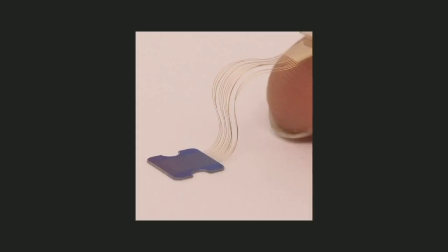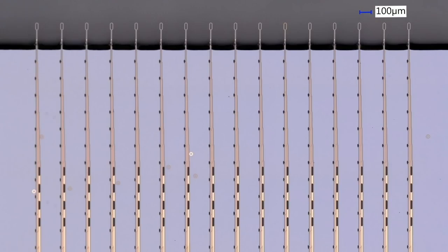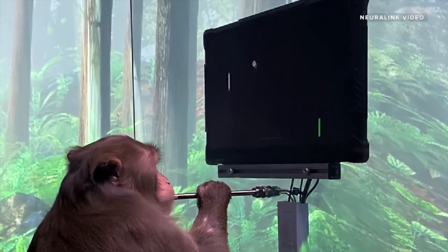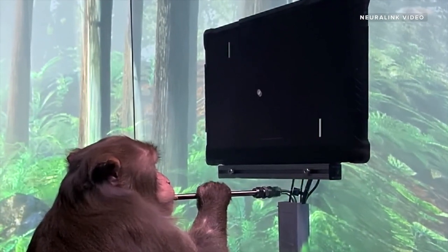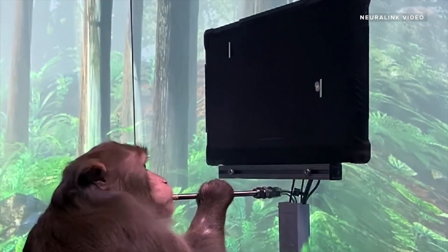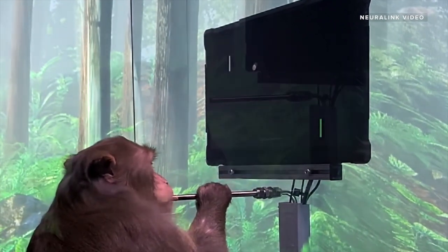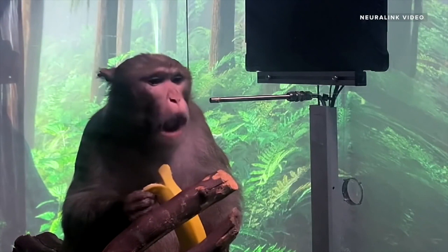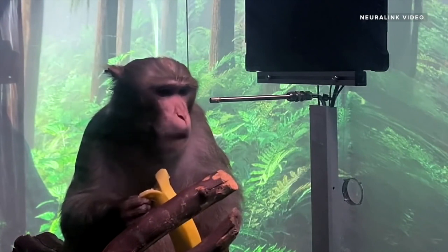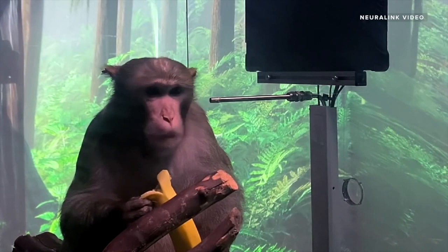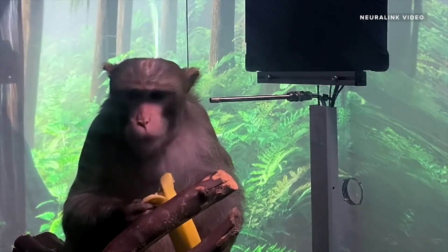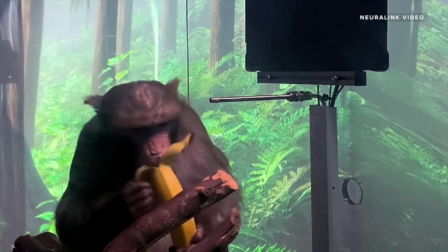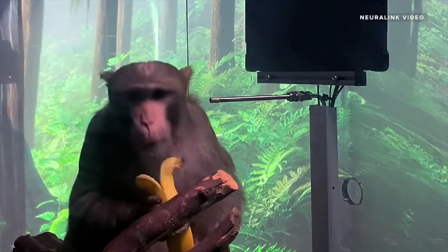One specific detail Neuralink has revealed is that they've been experimenting with adding a coating layer above the exposed portion of the gold electrode. The function of this layer would be to increase the surface area and total conductivity of this exposed region that's in contact with the brain. They do list several chemical solutions for this, which you can find in the paper. So that's how Neuralink builds their little electrodes. Well, it's similar to how Neuralink builds their little electrodes. Just remember, this paper is old, and they have definitely changed the materials and manufacturing methods drastically since the original Neuralink prototype. That said, the final microfabricated array for Neuralink in 2022 at least looks like this.